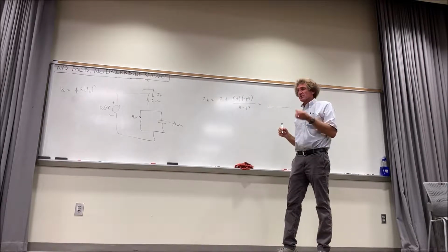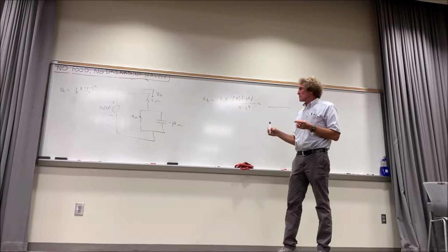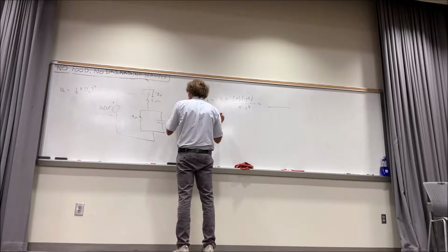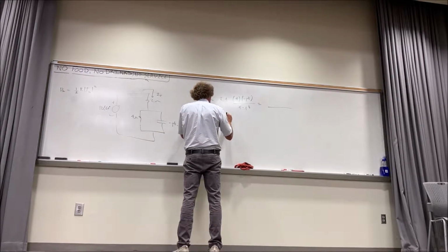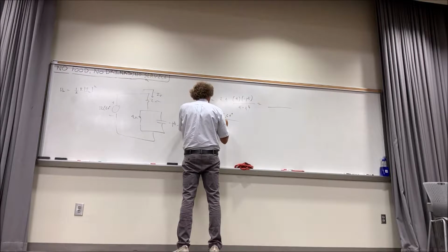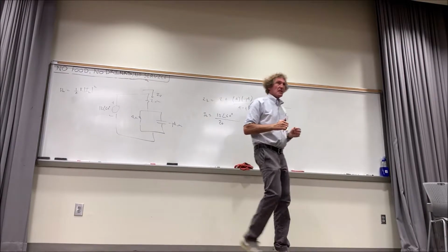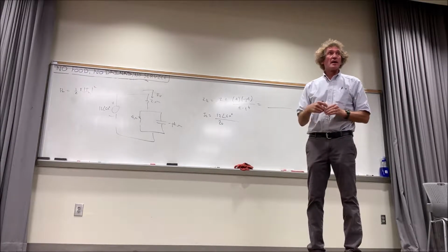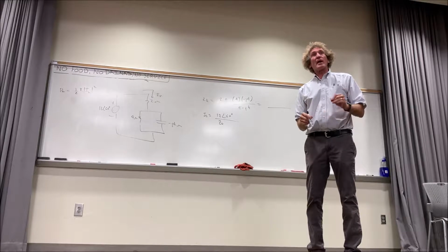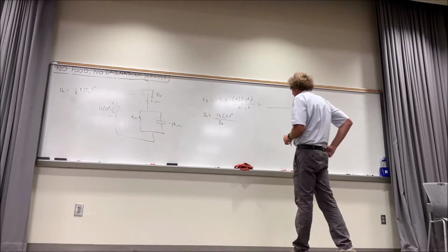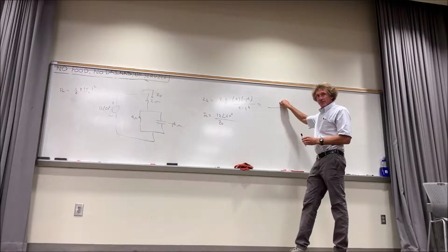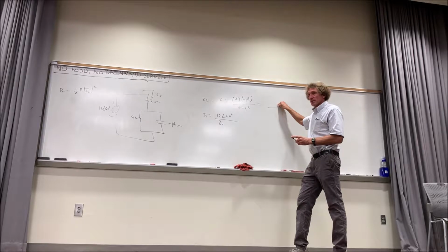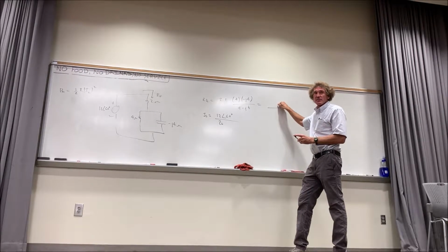You asked me about this. You see what I'm doing here? Once I have this total impedance, and we'll put a number in a second, the source current would be equal to 12 at an angle of 60 degrees over Z total. Everybody agree with that? Now your calculator should be able to do this rather quickly. First, you need a number for this. You can give it to me in real and imaginary or polar, either one. Go get your calculators out and see if you can do it.